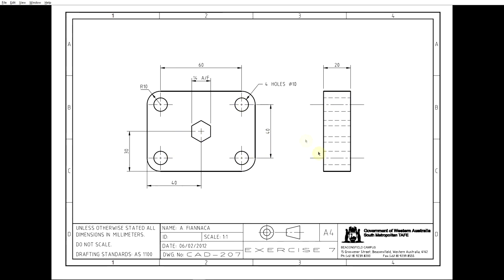Now when it comes to drawing this part, again, this is an orthographic drawing, so you can see here we're in third angle, so you're going to make sure these line up. You're going to draw your rectangle in there, and we will be projecting lines from these points straight across, from the center across, and all that sort of stuff. But in previous drawings we would draw them from there to the perpendicular point, and then we'd stretch them back using grips.